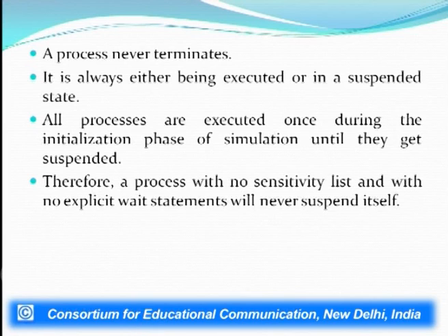Now what does that mean? For example, for a half adder where we say the process is sensitive to A, B, if an event occurs on A, then what happens? The statements are executed and then this process is said to be in the executed state. Once that complete execution has been done, the process will be suspended and it will keep on waiting on the sensitivity list for some other change to occur in either A or B. As soon as the next change occurs, it gets executed.